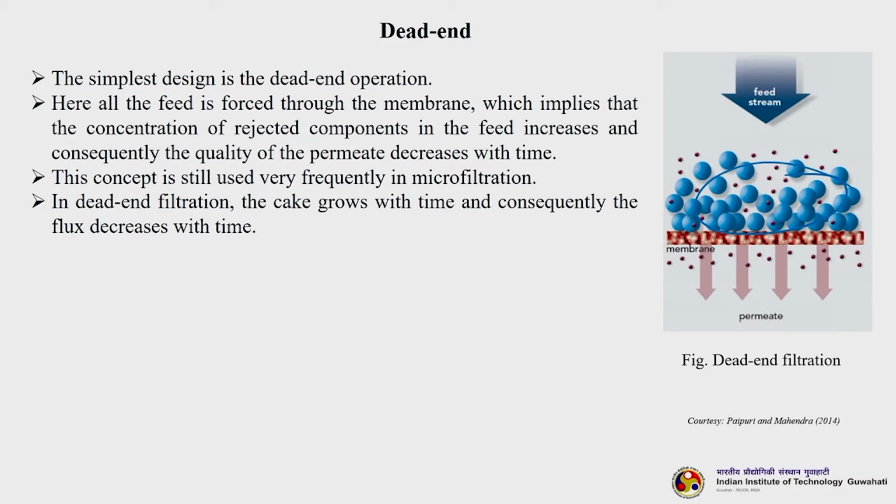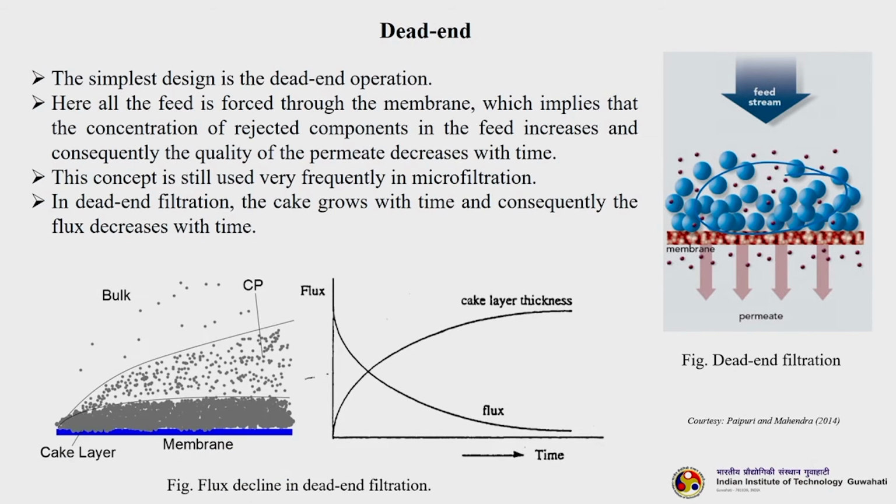The concept is still used very frequently for microfiltration systems. In dead end filtration, the cake grows with time and consequently the flux decreases. You can see how it looks. The flux decline profile is extremely fast and steep in the case of dead end filtration. You can see how the flux is declining, and how the cake layer is increasing,